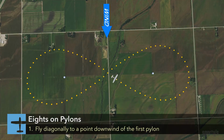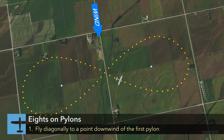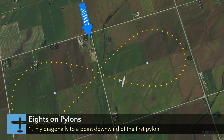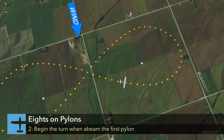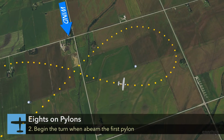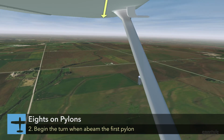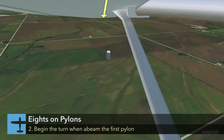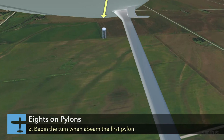To begin the maneuver, set up to fly diagonally on a leg crosswind between the pylons to a point downwind from the first pylon so that the first turn can be made into the wind. As the airplane approaches a position where the pylon appears to be just ahead of the wingtip, you should begin the turn by lowering the upwind wing to the point where the visual reference line aligns with the pylon. The reference line should appear to pivot on the pylon.